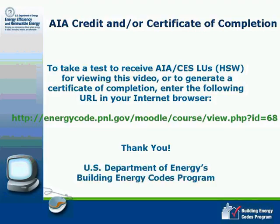There's a question about whether ASHRAE 90.1 allows use of over 40 tons of PTACs without an economizer, and I believe it does. I don't believe ASHRAE 90.1 has that same limitation. I know that is in several other codes, but I don't believe it's in ASHRAE 90.1 at this point.